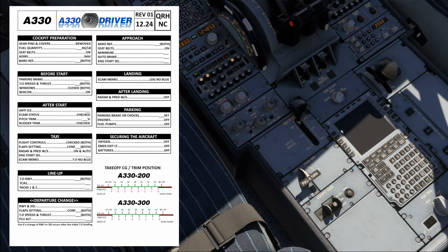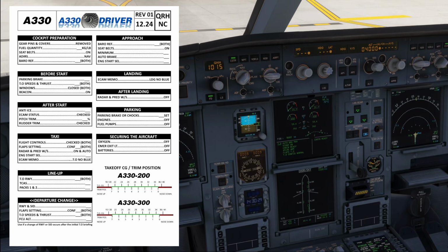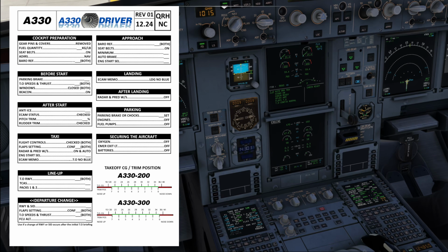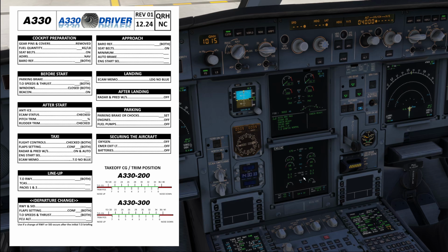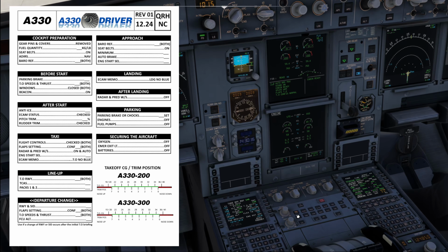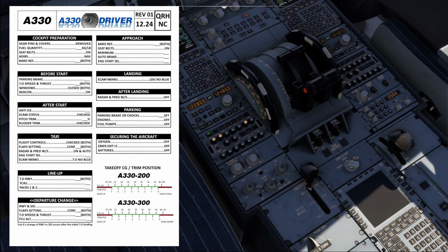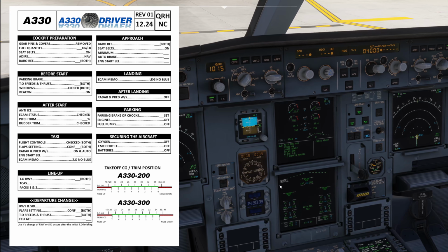If on the other hand the switch would be in the crank position, then, normally, the engine display should show on the ECAM display. Now, that means if the switch is in the norm position, you will not see the engine display and you will not see the ignition memo. The correct answer is either ignition or norm.